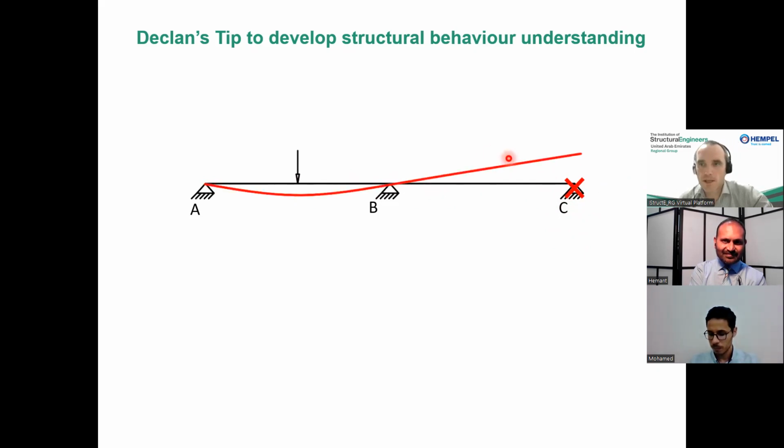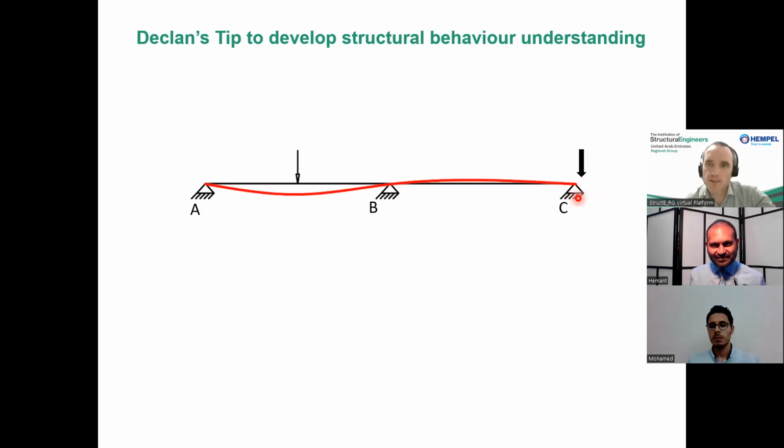And it would look something like this. You'll have some bending in the bottom of the first span. And then this cantilever, because of the curvature here, would move up. So without this support, the end of the beam moves up. So that would indicate that the reaction at point C is actually moving down. So in order to get this point that's raised up, in order to keep that at point C, you need to pull it down.